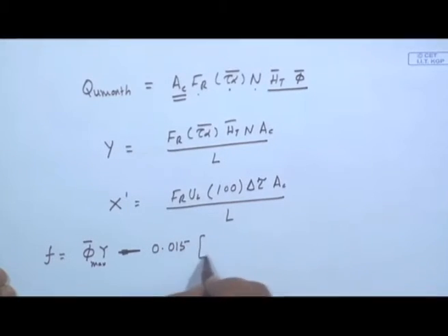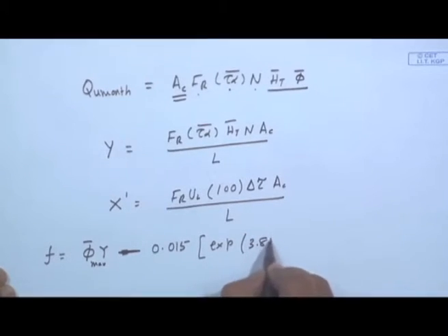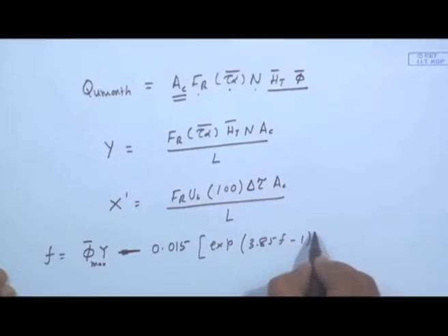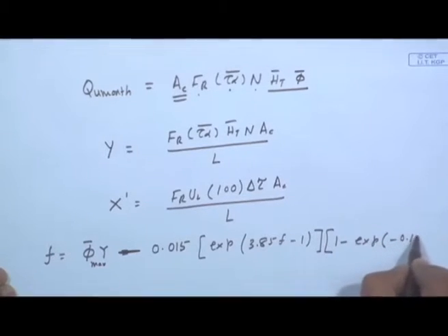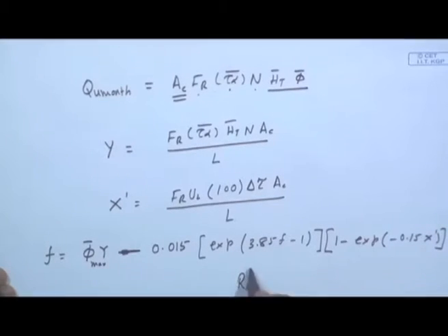I am rewriting it to just say that f is 1 minus exp of minus 0.15 x dashed times Rs to the power 0.76, where Rs is the ratio of standard storage to the actual storage. So, the correlation contains the effect of the storage.